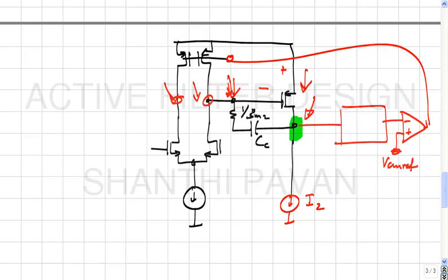In other words, you are not applying individual common mode feedback around each stage, but you are using one common mode loop to set the output common modes of both stages, because we know that in this particular circuit the output common mode of the first stage also changes the output common mode of the second stage. The reason is the second stage has no common mode rejection, because it is nothing but two common source amplifiers without the tail current source in a differential pair, which gives you that common mode rejection. Alright.